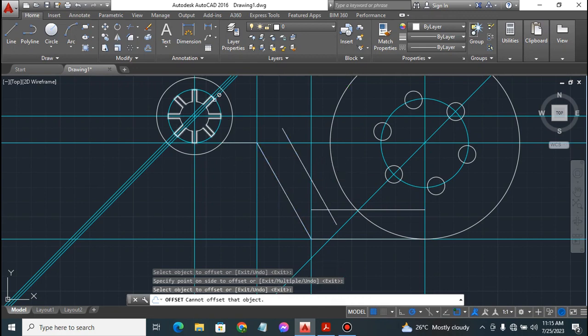Then over here, without offsetting, we can easily proceed, because the distance between these two construction lines is still 18 millimeters, so there's no need to offset. We just produce a horizontal main line there. Click the line tool, locate this point of intersection where my cursor is right now, left click on the mouse, then draw down to any point, any distance of your choice. Then left click on the mouse. That's all we need for now. Then you can press the escape key on the keyboard.